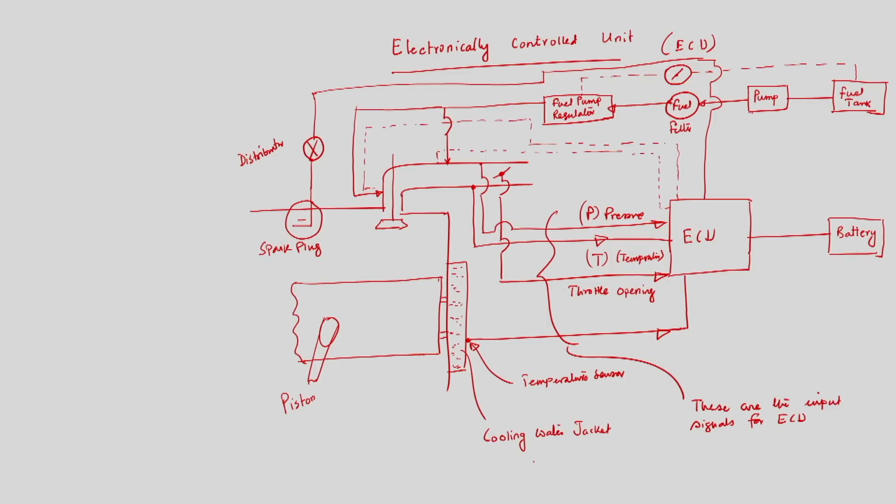That means the inputs to the ECU are the intake manifold pressure, engine speed sensor and temperature of the air in the intake manifold.